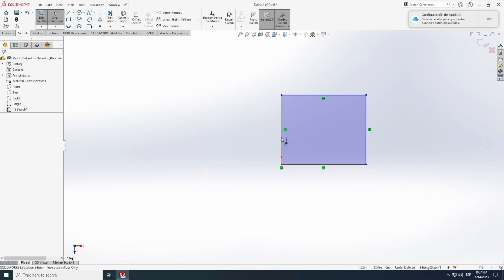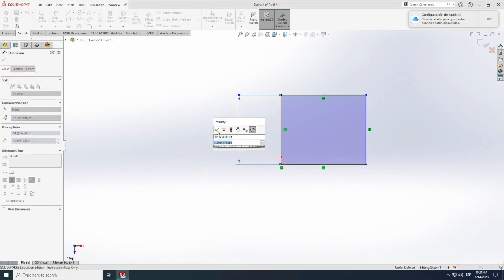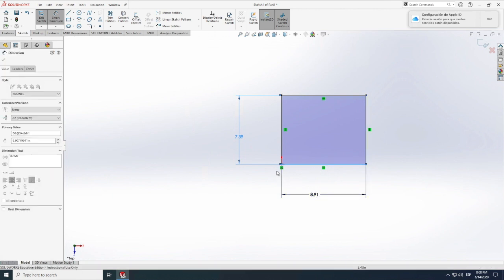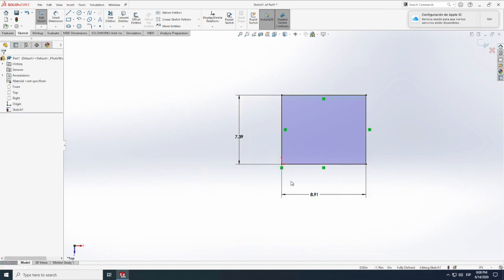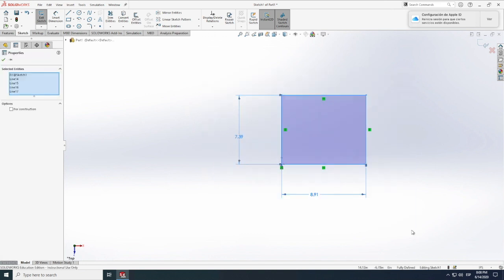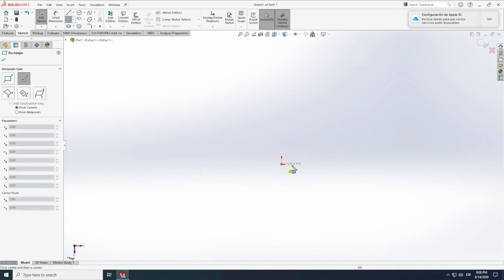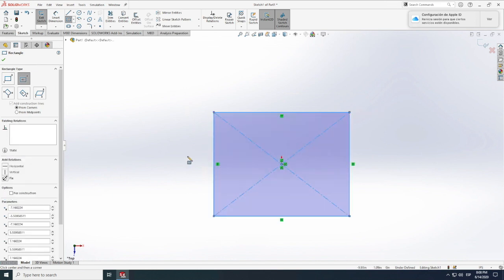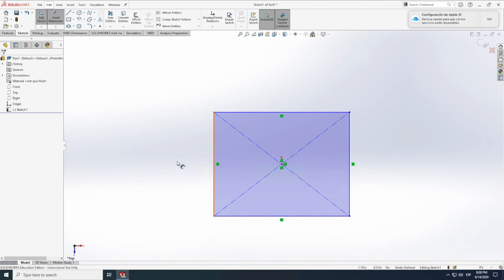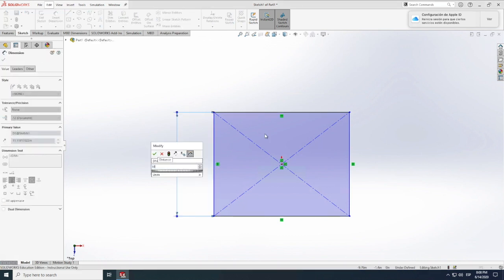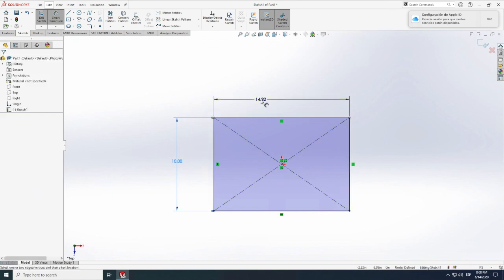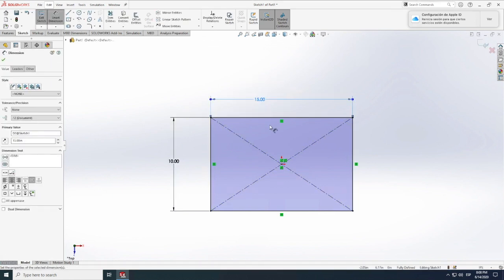And essentially, again, let's define that guy over there. Let's define in here, and we got ourselves a fully defined rectangle, because of course you need at least 2 points in there and 2 lines to define, and then you have the whole thing drawn. Similarly, we got our center rectangle, where we need to choose the origin, and then voila, we got a fully symmetrical rectangle along these 2 axes over there. As usual, let's give that a dimension of 10, and this guy a dimension of 15, and there we got it.